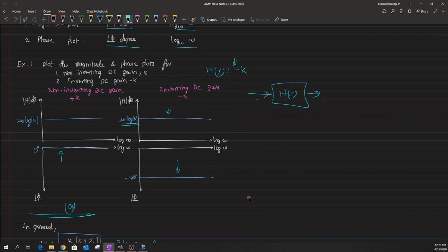There will be a phase shift of 180 degrees between the input and output. So what we really mean is that when I have a positive cycle followed by a negative cycle, the output will have a negative cycle followed by a positive cycle. It's something like a CS amplifier, which is an inverting amplifier. So there is clearly a phase shift between the input and output signal by an angle of 180 degrees.